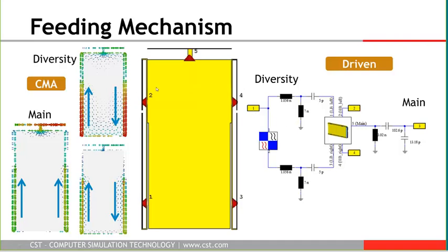You can also see ports 2 and 4 which are prepared for the higher band operation, but we will not show it here. We will use only the longer arms, ports 1 and 3, for the diversity antenna. Again, a matching network is necessary.